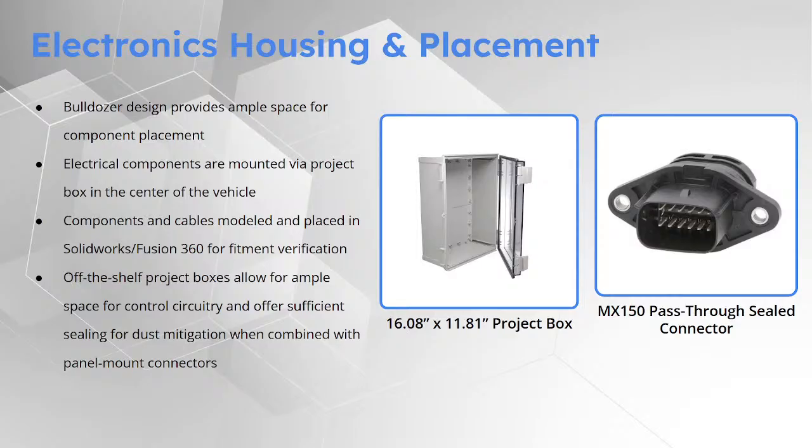Yeah, so as far as dust mitigation, those project boxes do have gaskets around the sides. They are entirely sealed in that respect. As far as wires going in and out, I've been talking about this to anybody who would listen, but Molex just released a new MX150 connector. It is the pass-through connector you see over there. The old panel mount connectors they had were good if you had sheet metal or real thin plastic, but those ones actually give you, as you can see in the back here, a good bit of clearance to go into whatever type of material you might be using. Those have built-in rubber gaskets on them. You just bolt them to whatever surface they're mounting into, and you've got a pretty good seal.